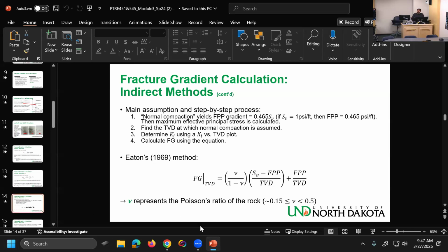Okay, now the people doing gelatin experiments like Kalu, that's as close to 0.5 as you can get. We assume in his work that we are really dealing with something like 0.5, 0.45, 0.47, and that's as close as you can get. In rocks, I wouldn't expect you to go over 0.4. For cement, that would be a very big exception. For cement, it's 0.33, 0.32, and that's pretty high. That's a very, very well blended cement.